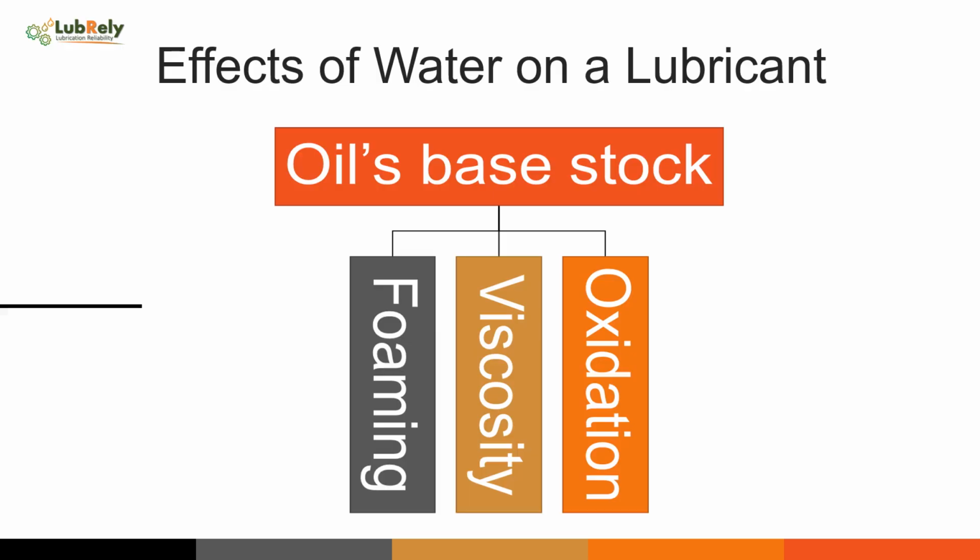Additionally, certain additives are hydrolyzed by water, resulting in additive mortality and the formation of acidic byproducts. Summarizing, water encourages rust and corrosion and will cause increased wear.